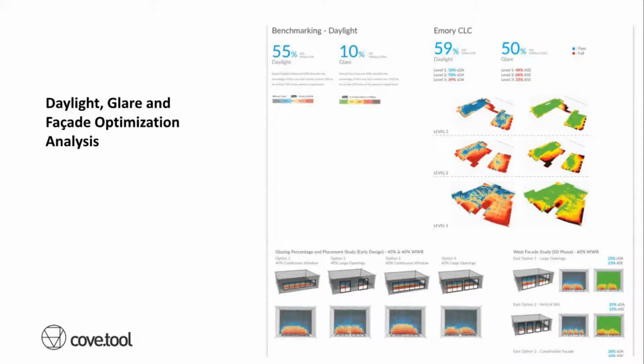Along with this, they also have a shoebox model that you can see on the bottom. This is mostly to study window to wall ratio as well as shading devices. All of these can be used to further study your EUI, or you can use your original base model you brought in. So the shoebox can translate into a better understanding of EUI or the impact it would have, but doesn't have to.